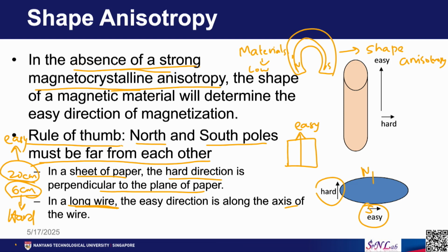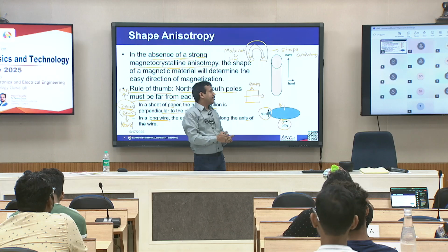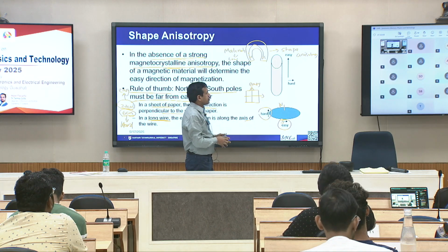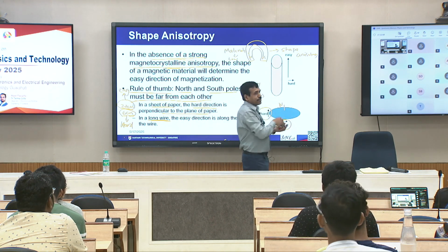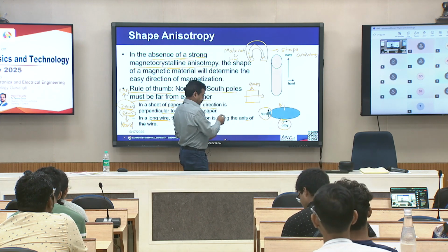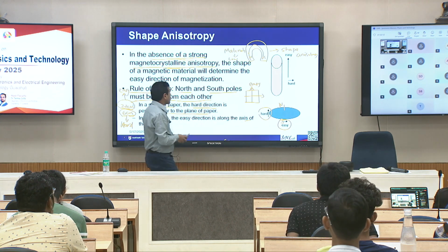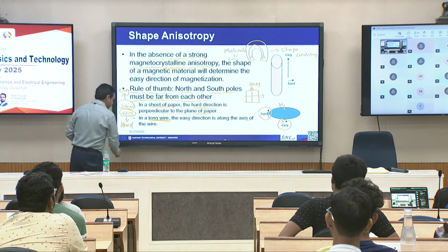You can easily measure the hysteresis loop along the marked direction and say 90 degree away from that. So, in single crystal it is easy to do. You know where is the easy direction, which is the hard direction, but in polycrystalline materials you do not know exactly, because you may have texture or you may not have texture.